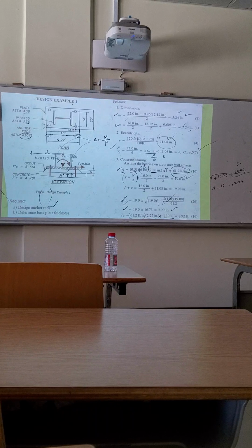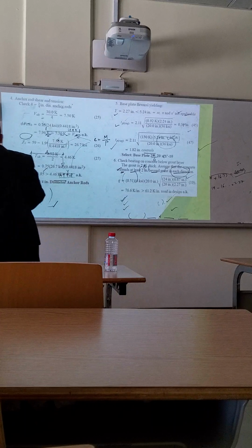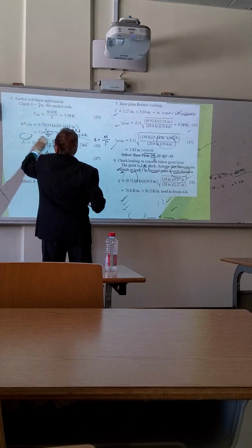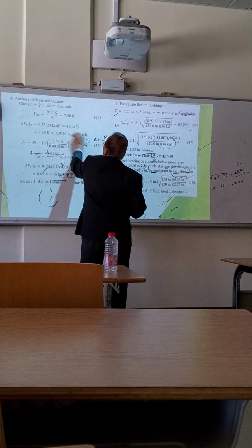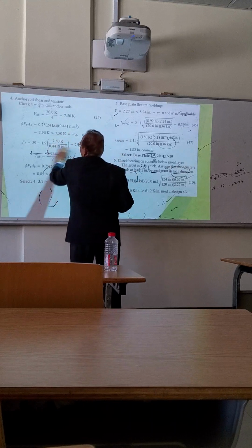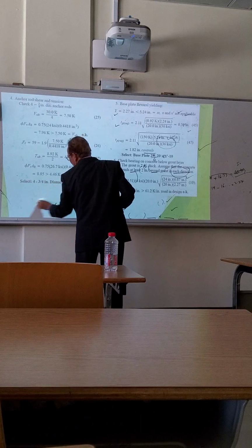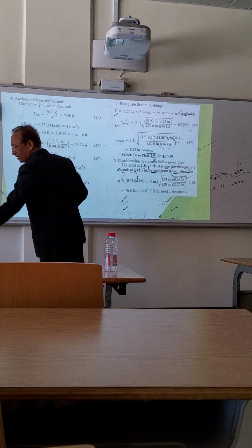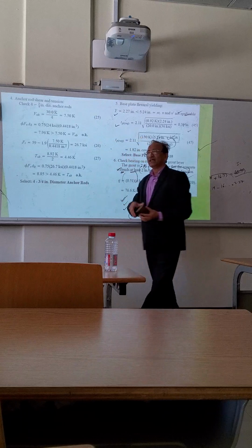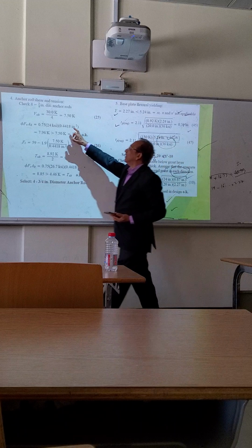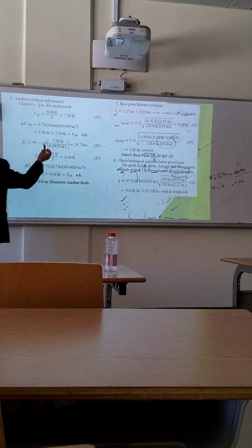You will select. But now in the question, the Fy value for grades will be according to this criteria of anchor rods. So here we now assume that we will be using 3/4 inch diameter rods. So we select the diameter of the rods or the anchor bolts as 3/4 inch. Somebody can say I will take 5/8 inch or 1 inch. Okay. So that will be your selection.